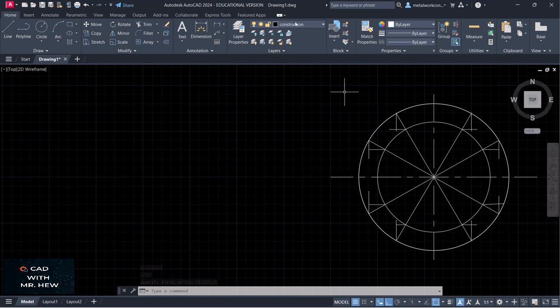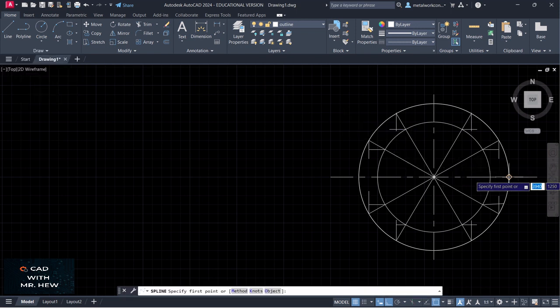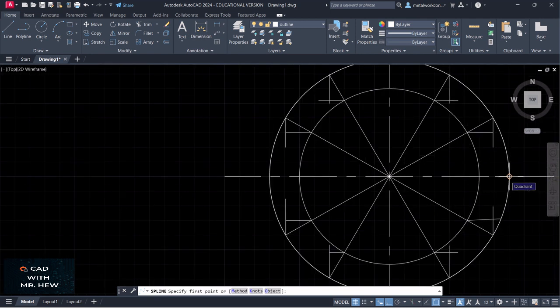So what we're going to do now, we're going to go to our outline layer, and we're going to go to spline, the one that says spline fit, and look how easy it's going to be done on the computer now. If you were using the T-square instruments, you'd use a French curve or a flex curve, or you can use freehand, all right? So we go here. We're going to zoom it up,